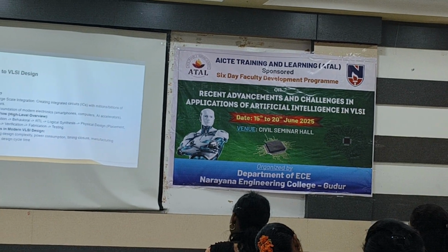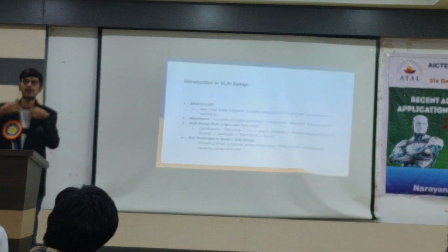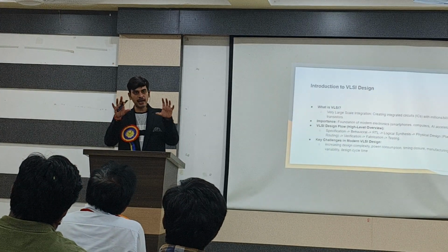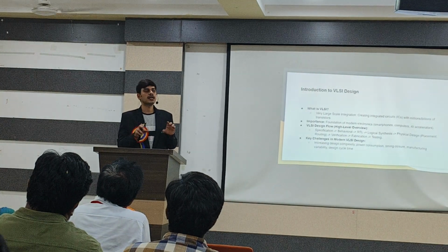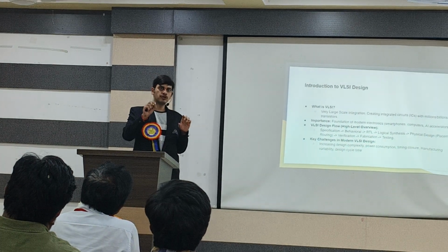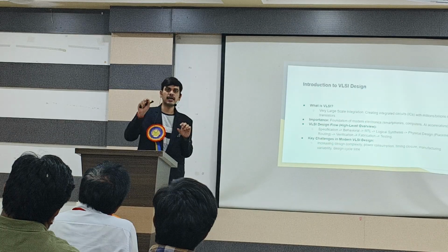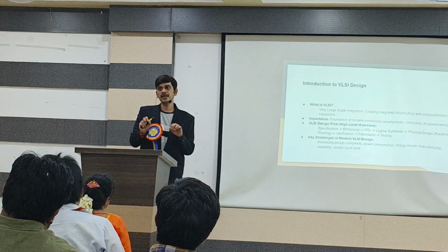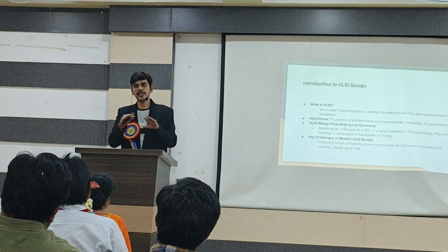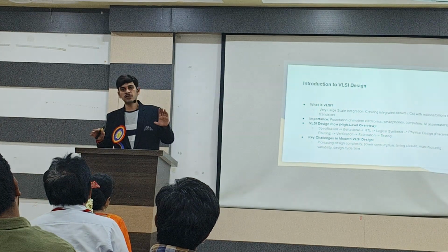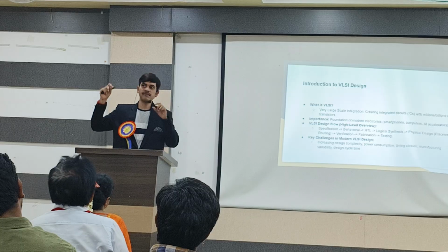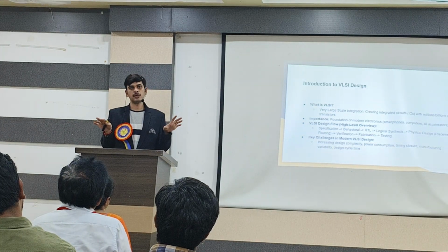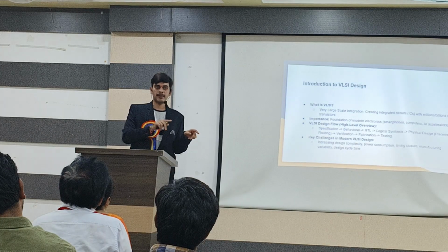At every stage, the timing model will give feedback to physical design, because the placement of the macros or cells depends on timing. If we do placement at random, without any guidance, then the timing will be worse, because a macro sitting in one corner may be interacting with a macro at the other corner of the chip, for example. So there is a wrong path, a critical path.